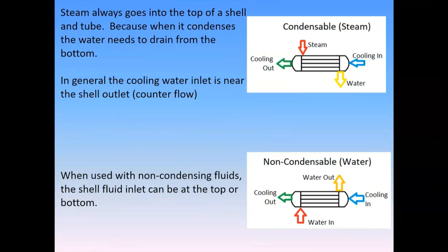Great, yeah. So at the end of the turbine, we have steam that leaves the turbine, and the condenser is always going to be located below the turbine, and the reason for that is that the steam has to come into the top of the condenser. So once it turns into water, we would collect that water after the condenser, and you would then have pumps at the very bottom underneath it to send it back through your process. So condensers always would have steam coming in the top, water leaving the bottom, and that would be essentially the application for this. A condenser is a very large shell and tube heat exchanger generally, but it's still usually the same style of heat exchanger.